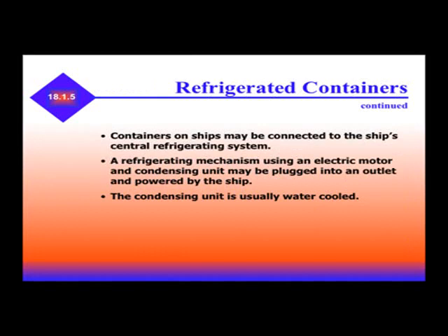Containers on ships may be connected to the ship's central refrigerating system. A refrigerating mechanism using an electric motor and condensing unit could also be plugged into an outlet and powered by the ship. The condensing unit is usually water-cooled.